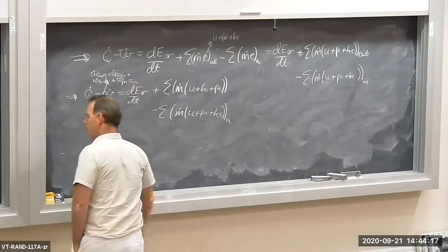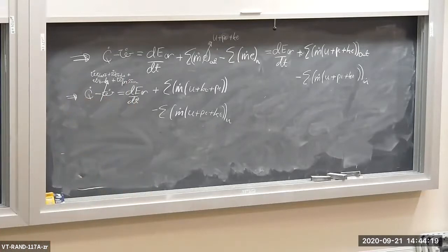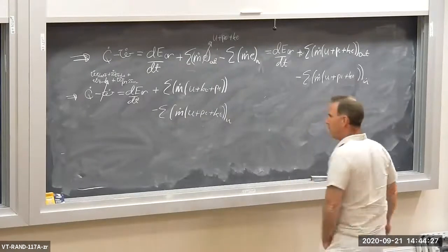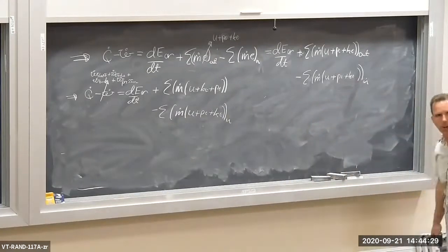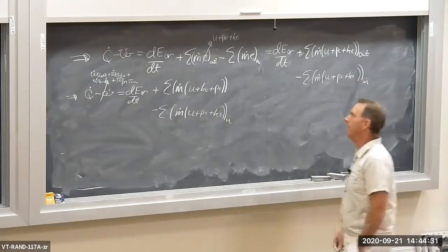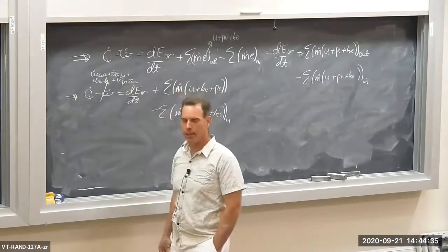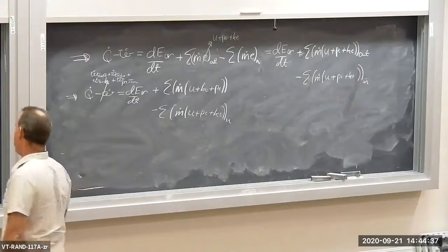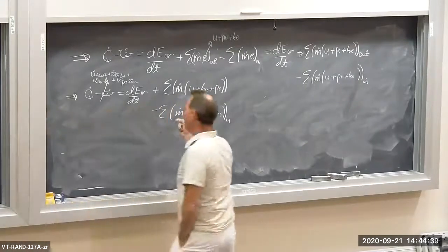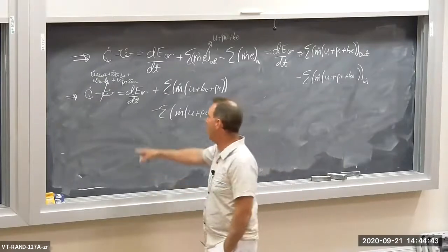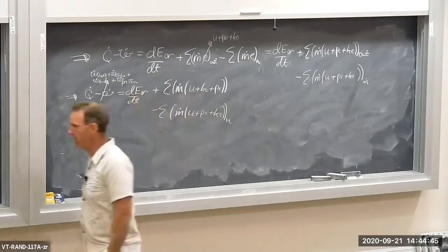The additional kind, due to pressure to force the flow in and then out of the control volume, is only present when you have an open system. Now we're going to calculate what this pressure power is, and then modify our energy balance so that it automatically contains the pressure power, okay?